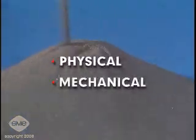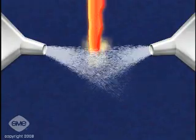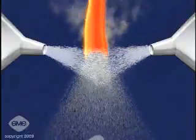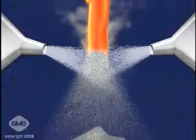Metal powders are produced by physical or mechanical methods. Atomization is the most common physical method. It involves breaking up a stream of molten metal with a jet of high-pressure water or inert gas, such as nitrogen or argon. Resultant droplets solidify and settle as powder particles at the bottom of a tank and are collected.